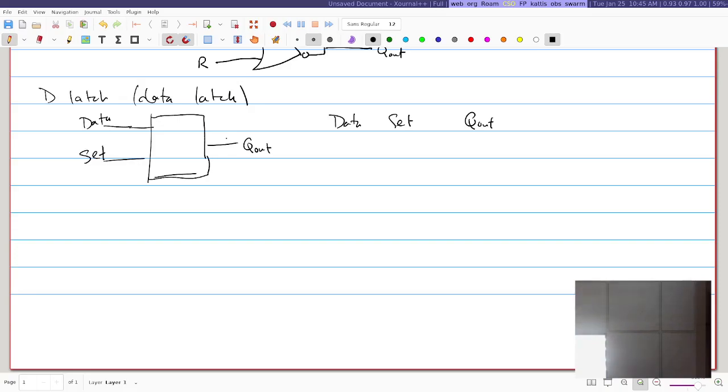You could just do something as simple as this. So here's an AND. This is an AND gate. So this is like whether we want to set, and there's an AND here that's just like, look, we're not actually going to set anything until the clock turns into a 1, right? When the clock is 1, anything that's coming in, we're actually saving to memory. But then when the clock goes back to 0, it shuts everything off, and we're not actually storing anything to memory. That's the time when we're waiting for signals to propagate from memory.